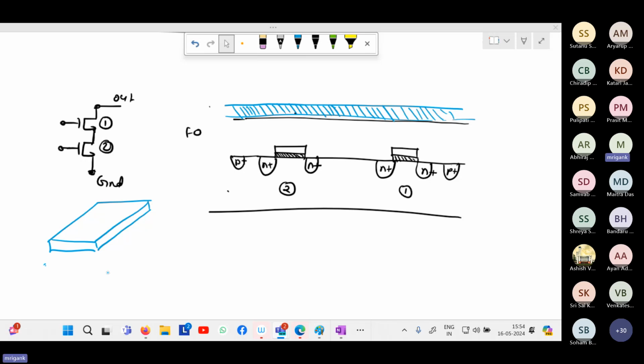So at the bottommost level, you are having the silicon. You are fabricating the transistors on that silicon. In that entire surface of this lower region, you will have transistors fabricated, different slots, different spots, different locations. You have many transistors fabricated. But now, in order to form the connections, we make use of these metal layers separated by field oxides. So FO1 is separating the silicon from the metal one. Likewise, FO2 is separating M1 from M2. Likewise, there will be M3, M4, M5, there are multiple metal layers.